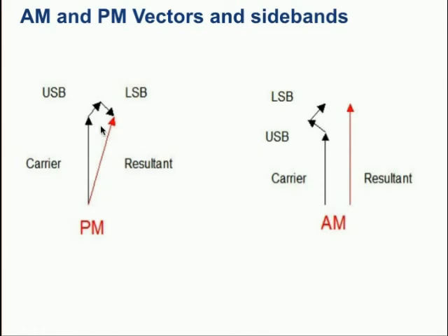Now, a useful thing this takes us on to is the way that phase modulation by noise of the carrier can be represented in terms of sidebands. In the derivation of the Leeson equation we're going to do, we're considering the noise in the active device just as a noise figure.